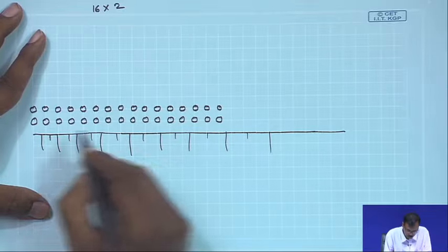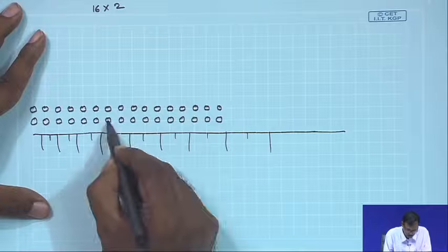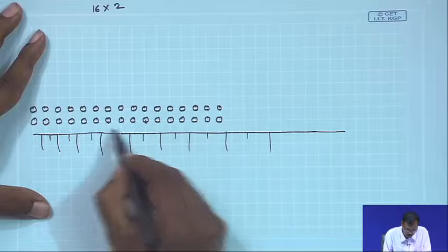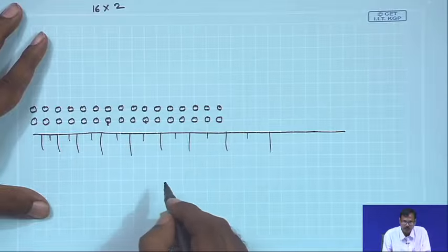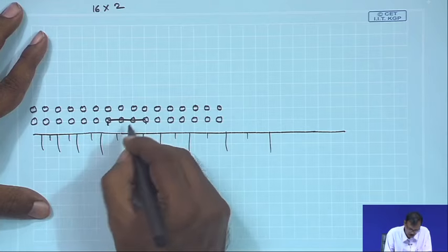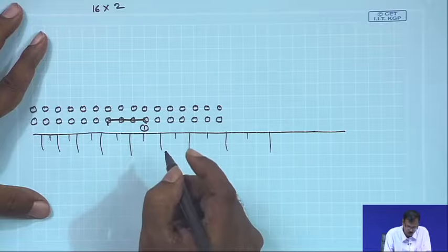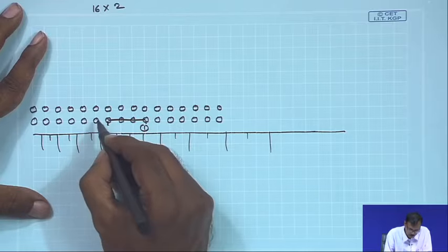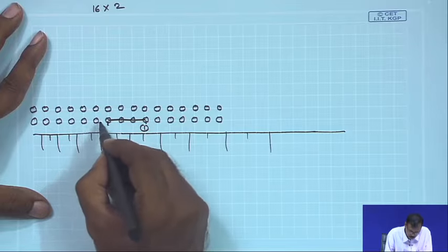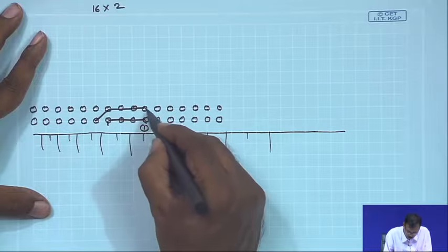So, let us consider 1, 2, 3, 4, 5, 6, 7. So, this is the 7th one. So, these 4 holes are centrally located. Let us blast it in one go. So, this is in delay number 1, these 4 holes will be blasted. Then we may go for blasting these holes together.